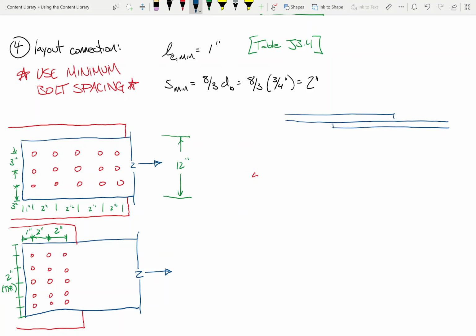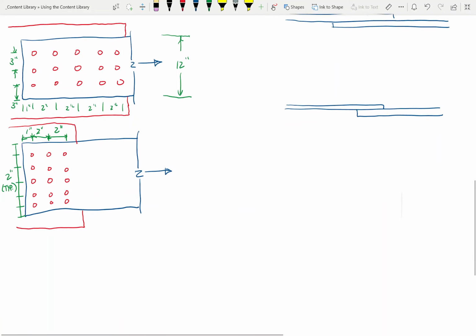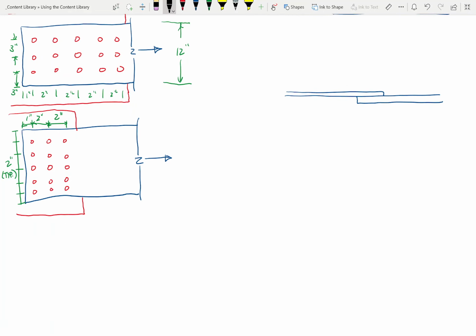This lap connection or that lap connection? This one has less wasted material. You see what I mean? So go with this one. I propose this connection makes more sense. Okay? Now, I am also proposing that, assuming it meets bolt bearing. We have to figure that out. So let's actually formalize that a little bit. Okay? So here's my trial connection.